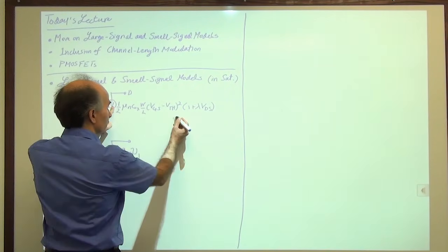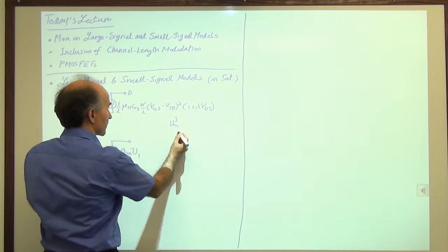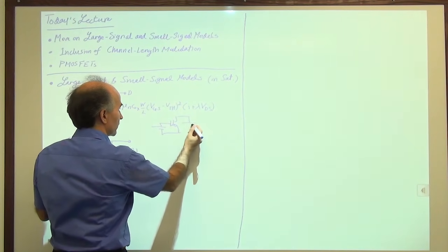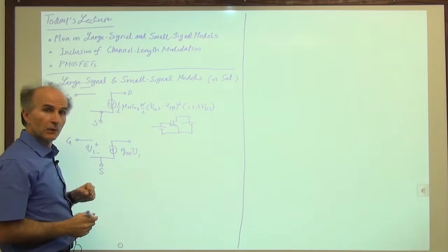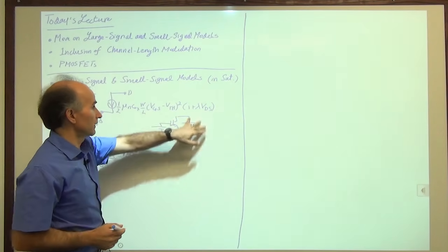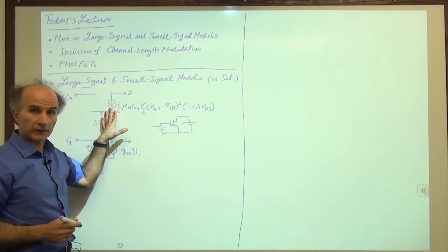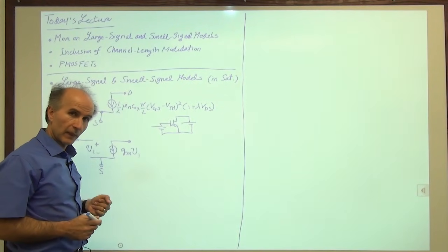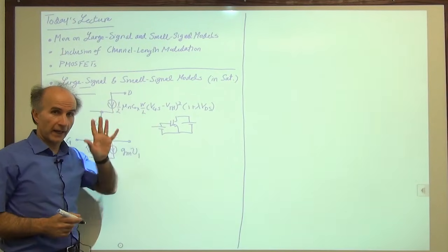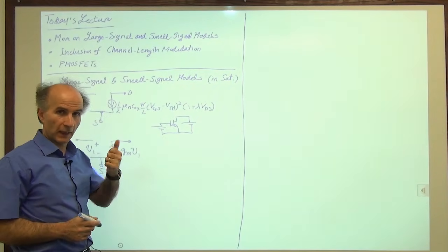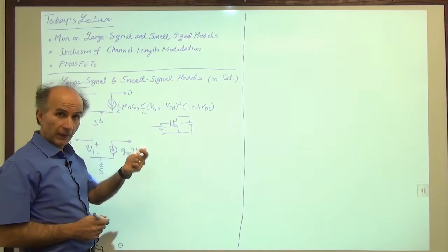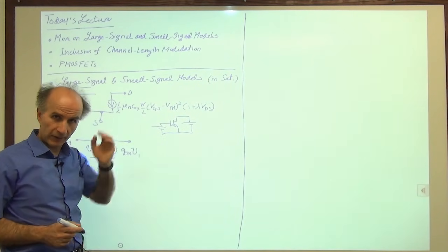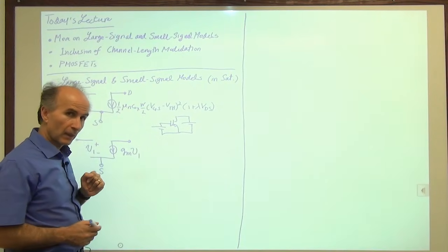So this model would apply to a situation like this, where we have a constant battery between the gate and source, another battery between drain and source. So we know VGS, we know VDS, we can go ahead and find the current. And that gives us all the bias conditions of the device. Now, that's done. We have the properties we need. We can find gm, because gm can be calculated in terms of VGS minus VTH or ID, all the equations that we saw before.